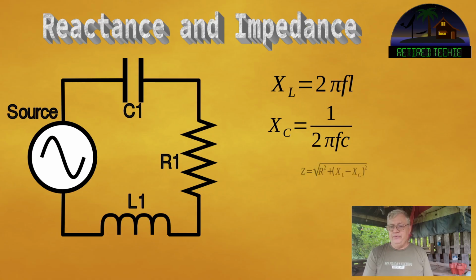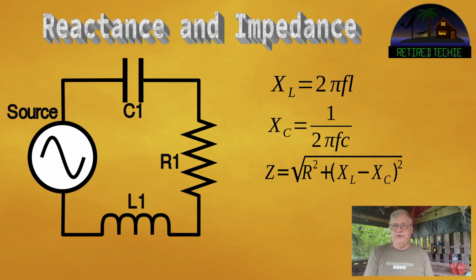And to get impedance, impedance is made up of two parts in an AC circuit, resistance and reactance. So we have the square root of R squared plus X sub L minus X sub C, that value squared. Again, we take the square root of it, and that equals impedance, or Z in ohms. I just want to mention these here. Like I say, that's a separate video, but it is a part of a circuit if these type of components are available, and there's some interesting stuff that works out from these equations.